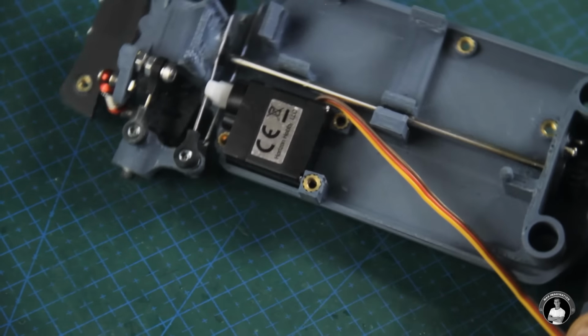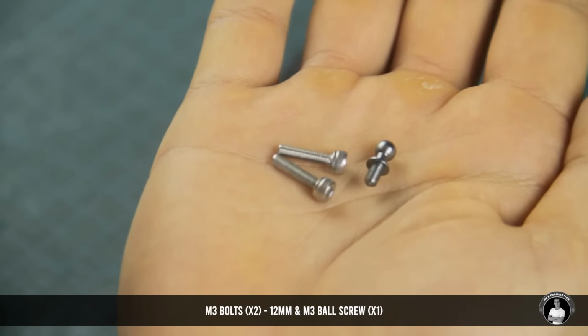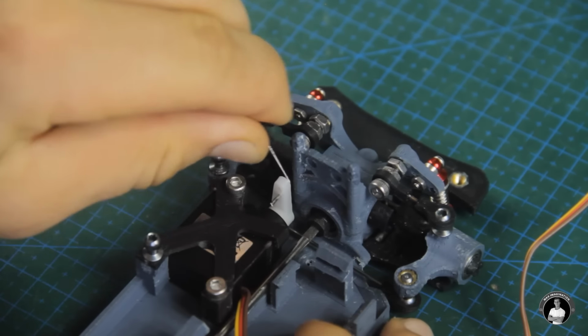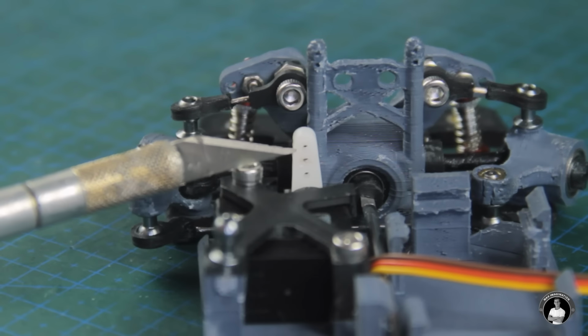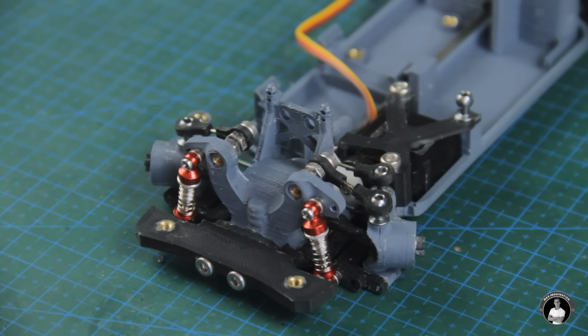We can follow up with the servo mounting piece, which screws on with a couple of bolts and a ball screw. Then the servo link can get attached to the servo horn at the right distance apart from the left wheel cup with everything pointing straight. The servo link can actually be adjusted a notch up the servo horn for a wider range of steering.